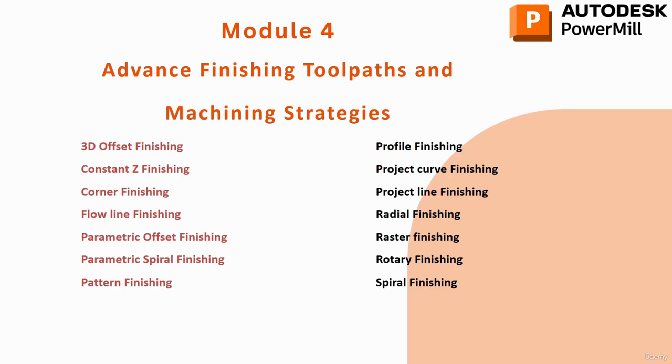So today we are going to start another operation which is known as the profile finishing operation. Very much similar to the pattern finishing operation, but it only follows the edges and profile, either the inner profile or the outer profile. The surface which you select, the cutting tool just follows that surface and cuts down that material.